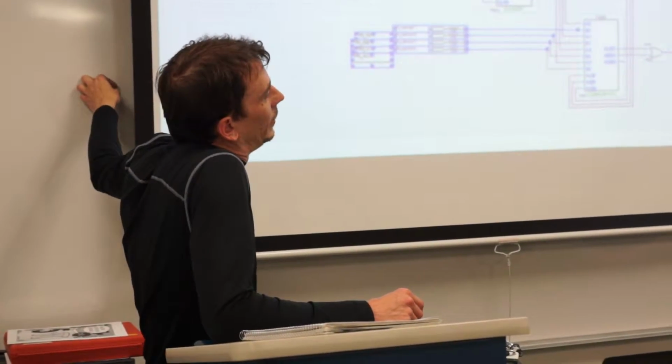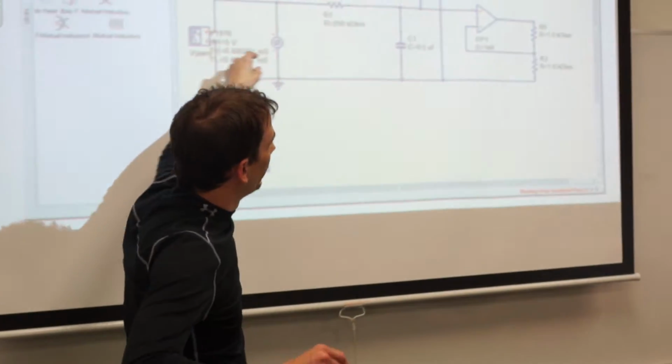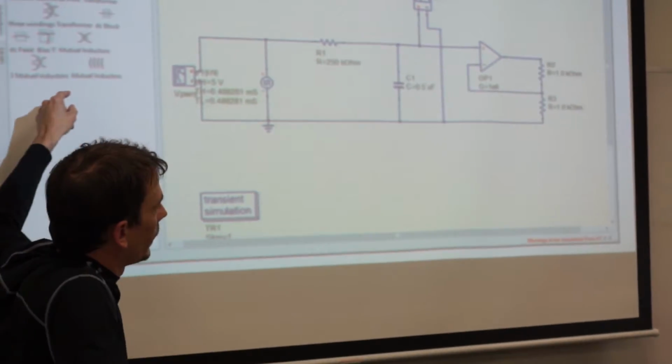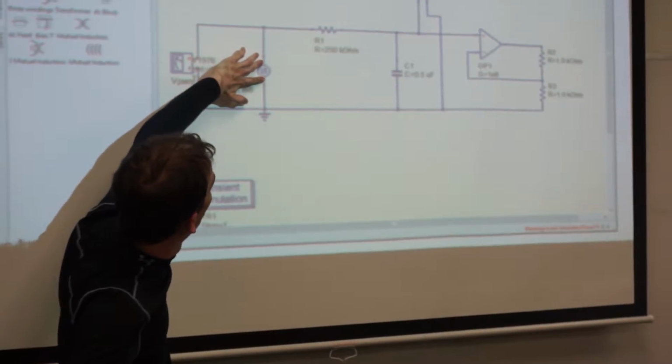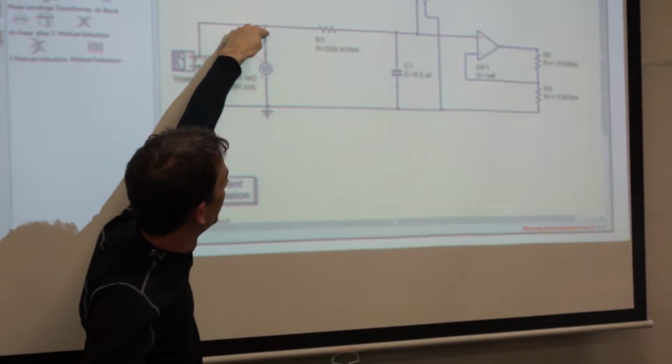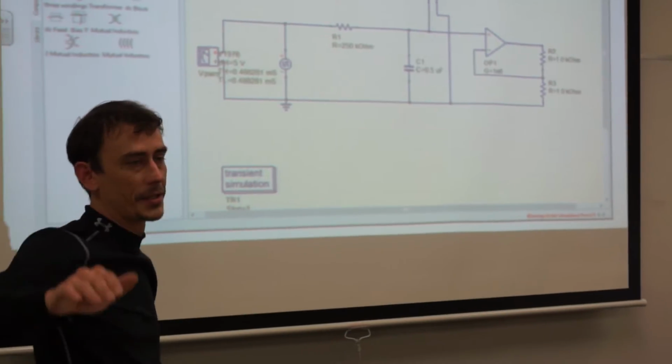The next circuit we have, it's an RC circuit, which we've been getting familiar with in analog class. Right here is the whole digital circuit from the other. And this is providing that pulsing 0 or 5 volts into this. And because of the analog properties of the interaction between our capacitor and our resistor, that is going to smooth it out into a constant DC voltage.